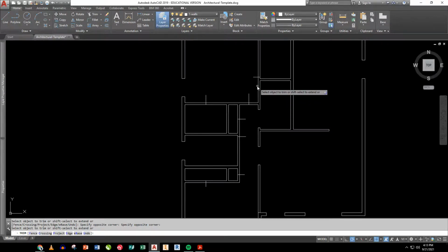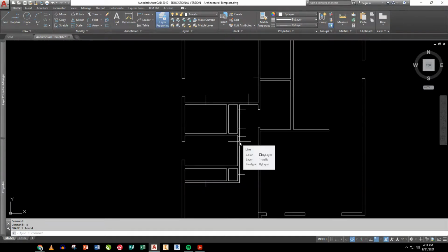these two lines. And now I've got to do some offsetting, and I'm going to go 18 inches from this to below and this to above. And I'm going to erase this one. So that marks that doorway. Okay, this doorway into this bedroom, this doorway into this closet, this doorway into this bathroom here are all 2'6" doors. Okay, so I've got to do a couple things here.